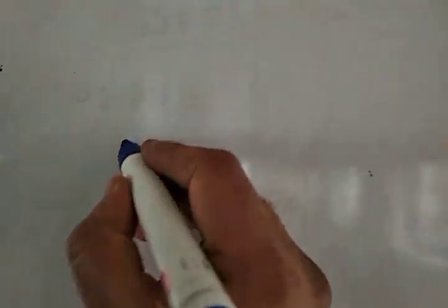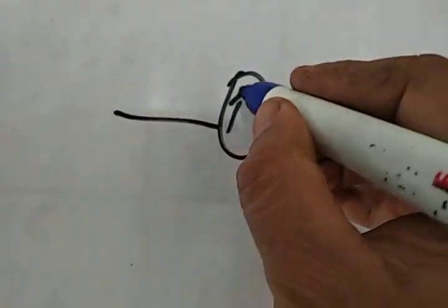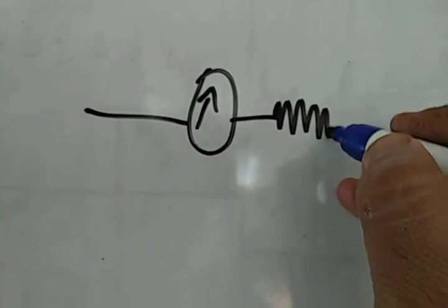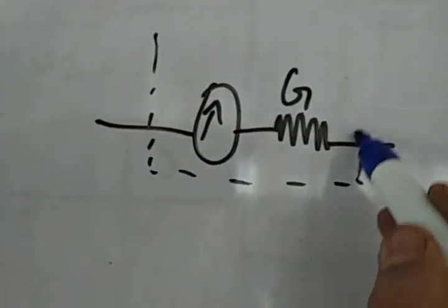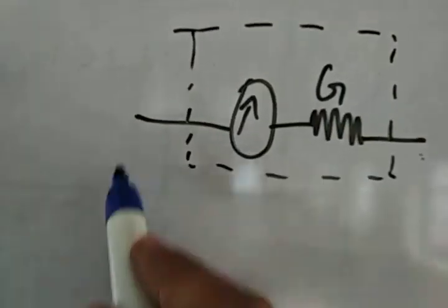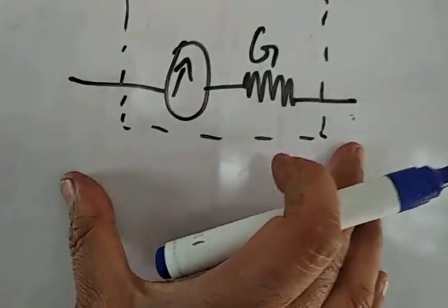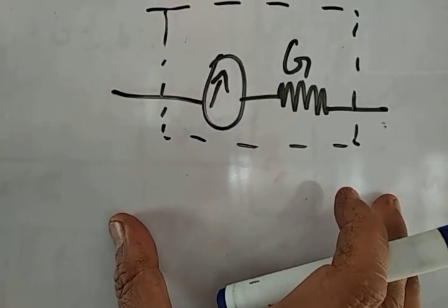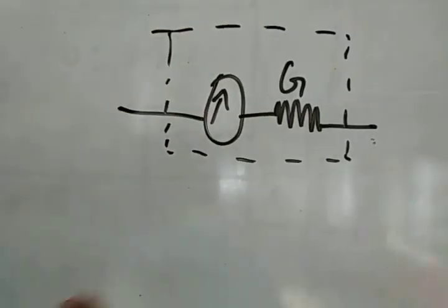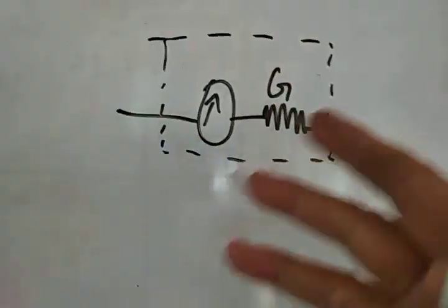Let's see. This is our galvanometer. It has some resistance, we know 66 ohms. This part is our galvanometer. Now, this can handle only a maximum of 41.6 millivolts. So we need this galvanometer to handle more voltage.